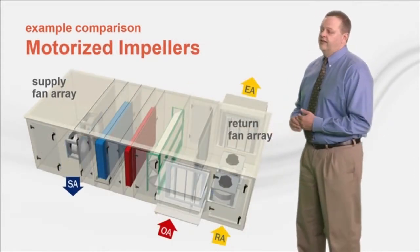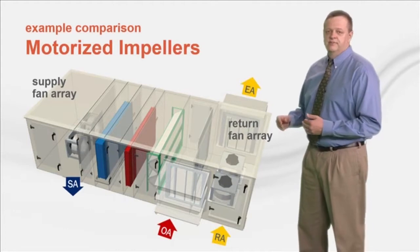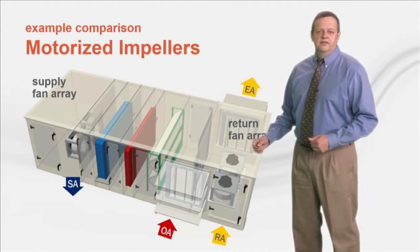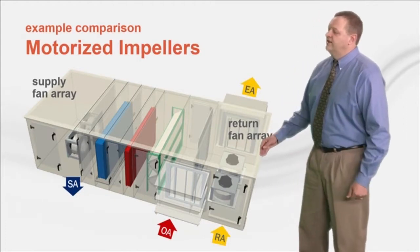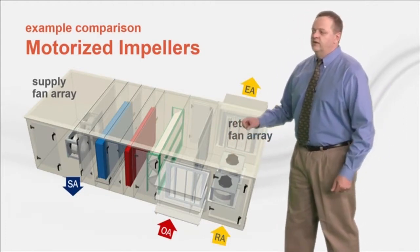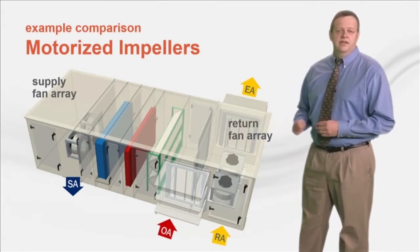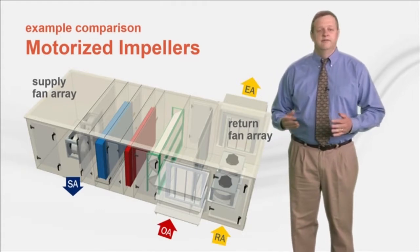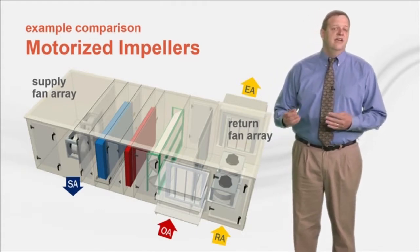Now this second air handler uses motorized impellers for both supply and return, again each being an array of 2 fans. Notice how the motorized impellers allow the return fans to be oriented vertically, which avoids the need for an upstream plenum section. Plus, there's no additional space required for variable speed drives, since that control is integrated into the fan assembly itself.